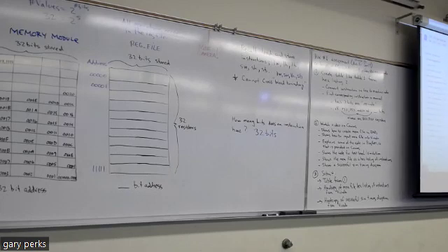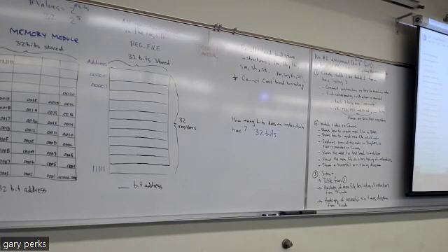Now, for each address, you see these numbers here. These numbers are in hex. 00500293, that's in hex. 06400313, that's in hex. So why are there 8 hex characters at each address for an instruction? Because each instruction is exactly 32 bits. This is just showing you the 32 bits for each instruction in hex. Instead of writing out 32 zeros and ones, it was put in hex to make it more condensed.